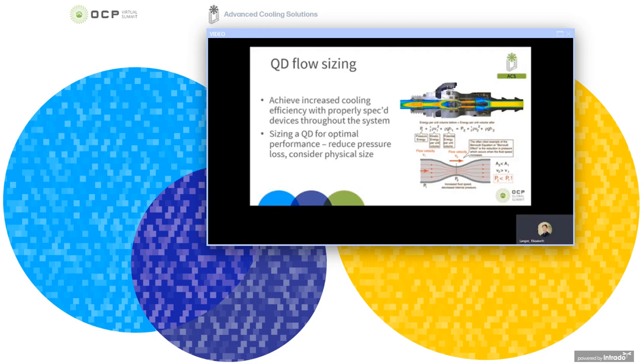Additionally, as we see on the right-hand side, and from our friend Bernoulli, we can understand the relationship of fluid velocity to fluid pressure. As the fluid velocity increases, for example, when flowing through tight spaces, small fittings, and orifices, the fluid pressure will actually decrease, contributing to the overall system pressure loss. And vice versa, as the flow path becomes less restrictive, the fluid velocity will decrease and pressure will stabilize. This concept is fundamental to understanding and being able to optimize flow paths within quick disconnects to produce the least possible pressure loss across the set.